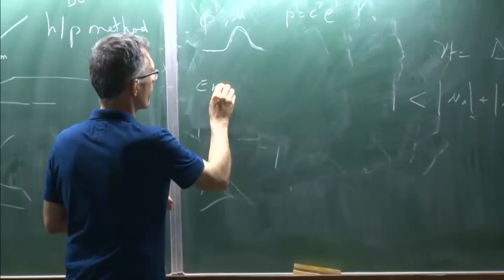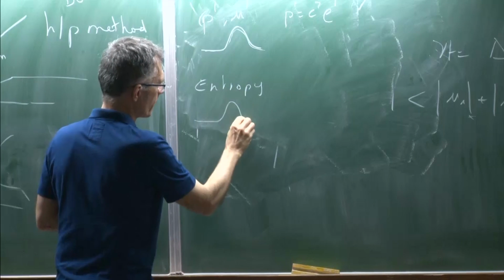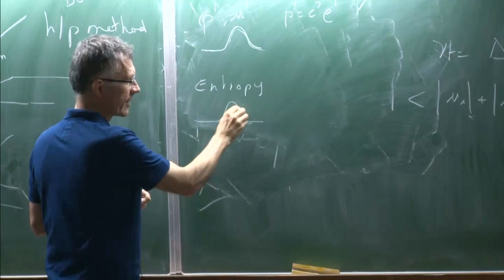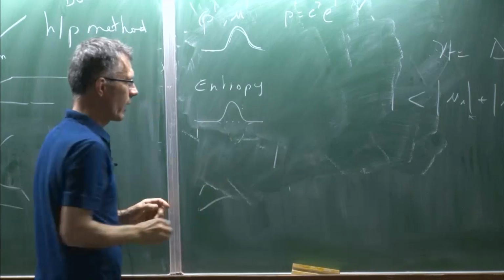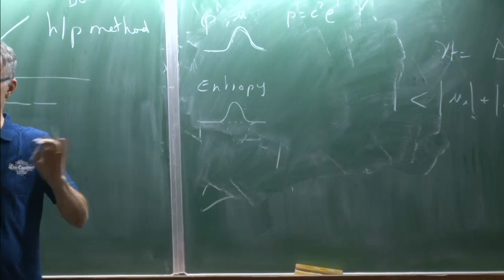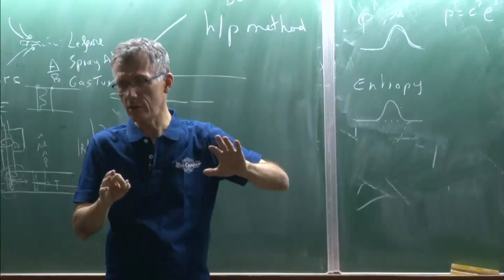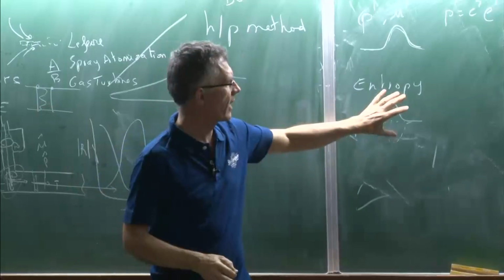Entropy waves are such that the temperature is going up and density is going down, so that you have exactly a constant pressure. So for entropy waves, there is no acoustic component. They live in different worlds. If the amplitudes are small, these travel in the flow, and those travel in the flow.